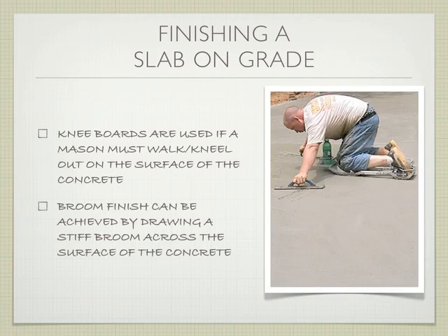But the purpose of something like this is that you're spreading out your weight across a larger surface area. And so the concrete, as it's curing, can support your weight if it's spread out. But if you do a point load, it's still going to depress. If you've ever worked with concrete, like when you were a little kid and you wrote your name in it or something like that, you know that as it's curing, you have a little bit of time when you can still do that. And that's because it's a point.